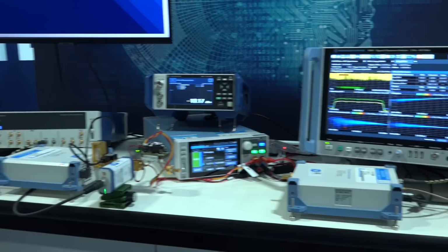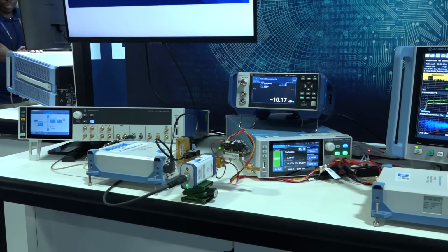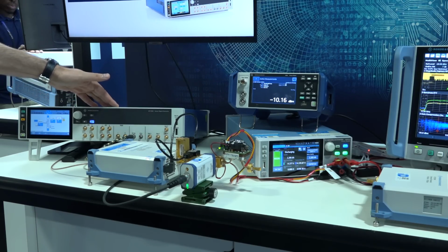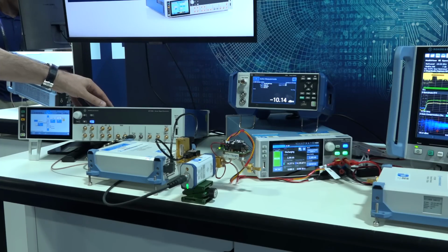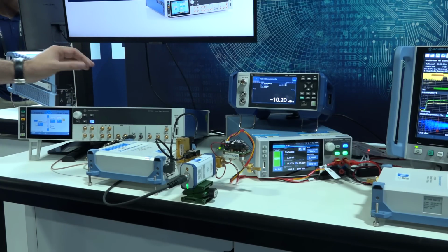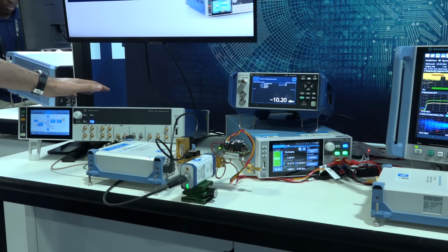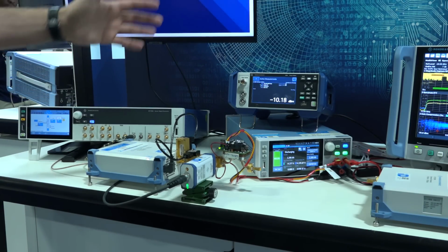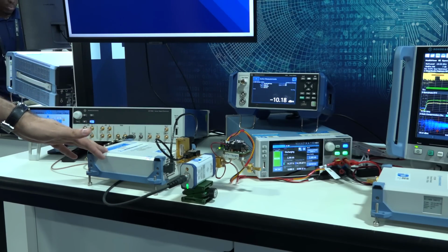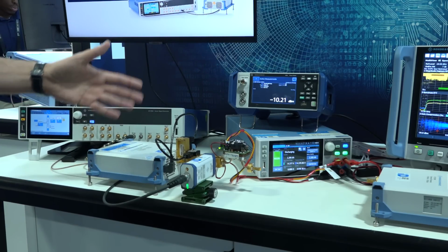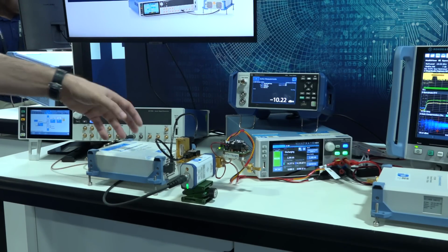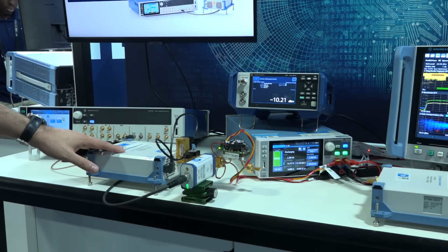Now, another thing to pay attention to is the release of this particular unit, the SFI100A, and this one has a built-in mixer that provides an IF output between 11 to 14 gigahertz or so. So it basically has an IQ DAC inside that upconverts into a fixed IF frequency that you can move around. The idea is that this would become the IF input for a wide range of frequency extenders that Rohde & Schwarz sells. So you can essentially buy this, connect it to this, and do modulation up to 10 gigahertz of bandwidth, anywhere in that range that you want. Pretty powerful when you combine it with something like the FE170, for example.